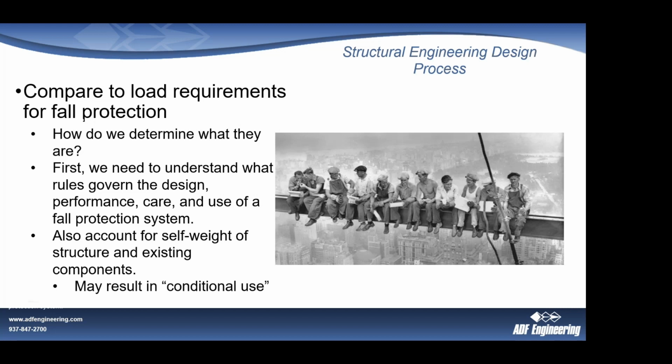Sometimes when we're at an existing site, or a brownfield site, we not only have to take into account that load, but the weight of other materials, such as a large piece of equipment, the heavy weight in a flooring system, or any kind of live load that might be on that same floor. For instance, the beam that we're attaching to may also be part of a floor system or a roof system.